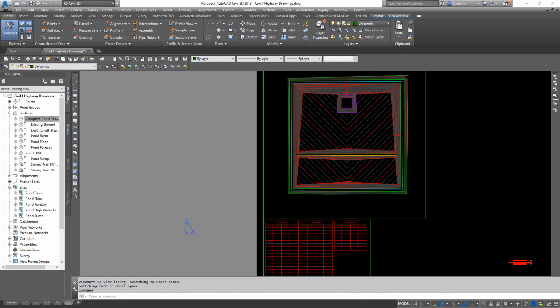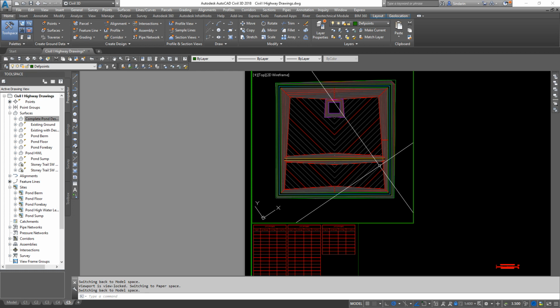In this video, we're going to go about cleaning up our pond since it looks like a bag of Skittles. It's colored blue and green and yellow and purple, and it will print with those colors since the options we chose. So we'll go about cleaning that up. I have made the outside edges square, so you can go ahead and do that as well. And then finally, we'll create some layout points, and we'll populate this table down here with our layout points for the pond.